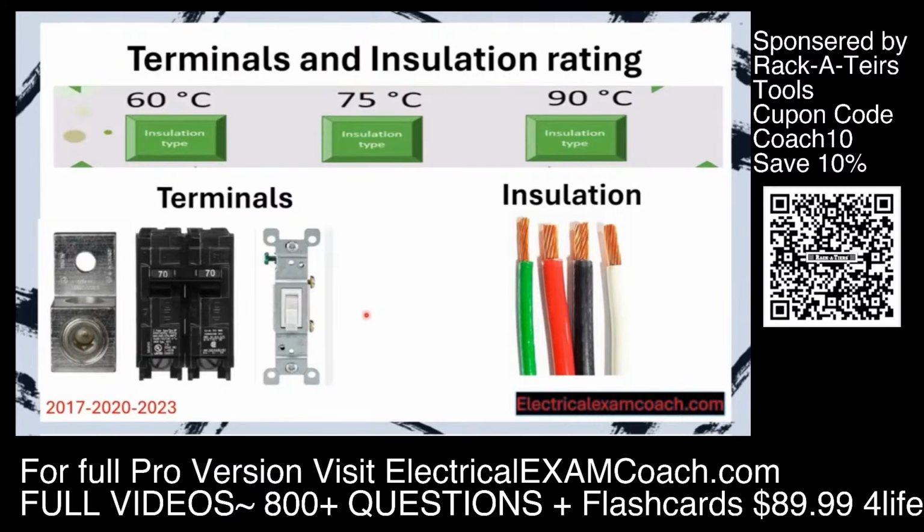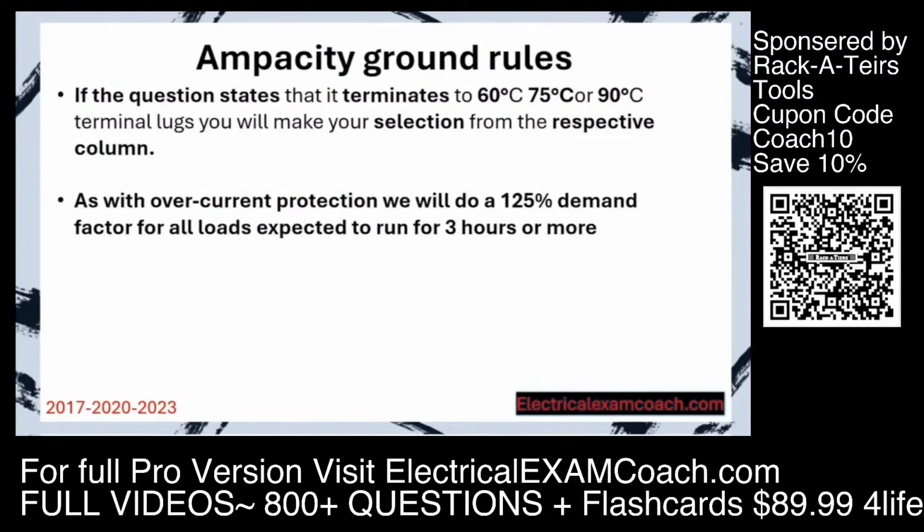But for right now, what I want you to remember is we're going to match the column that we use based off the terminals that the device is rated by. Regardless of what the insulation is, we can choose from whatever column that the terminals are rated by, unless modified by another code. Now let's lay some ampacity ground rules. Unless modified by a specific piece of equipment or another code, these rules will apply generally. If the question states that it terminates to 60, 75, or 90 degree C terminal lugs, you're going to make your selection from that respective column.